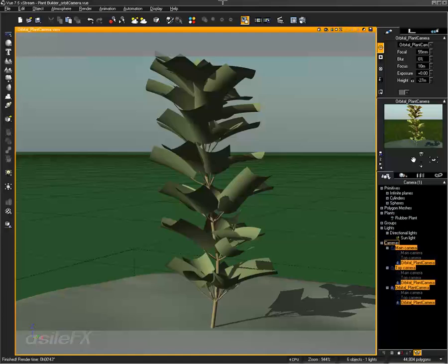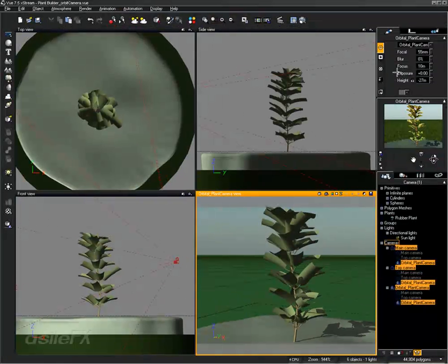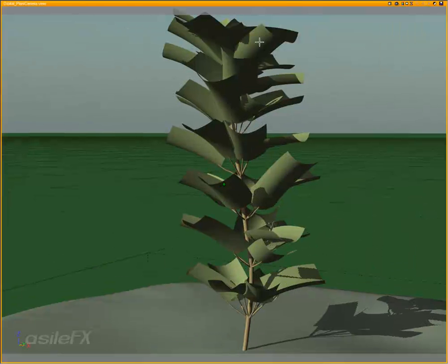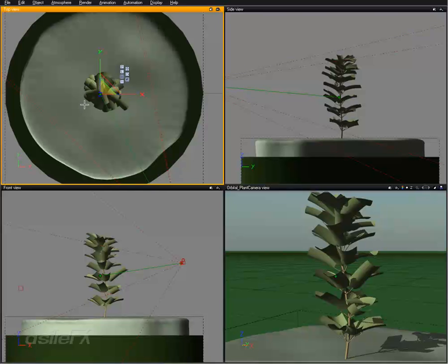If you want to position it, we'll select the camera. We're going to go to the numerics tab, select the pivot point, turn it on, and all I did was position in the 4 viewports and move the camera so that that pivot point shows up in the center, which is the projected pivot from the camera, basically to the center of the scene.